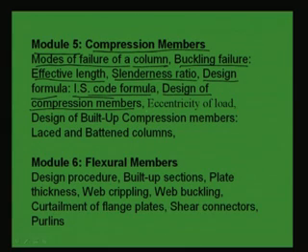Then eccentricity of load. If eccentricity of load comes into picture, then we know that additional load will come due to eccentricity, in terms of moment. So, that also has to be taken care of. Then design of built up compression members. Built up compression members means when a single rolled section is not sufficient to carry the whole compression load, then we may have to go for built up sections.